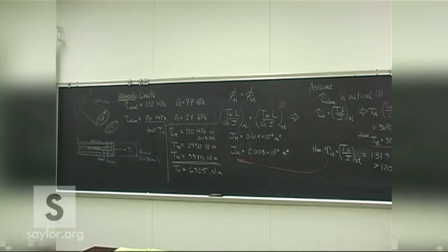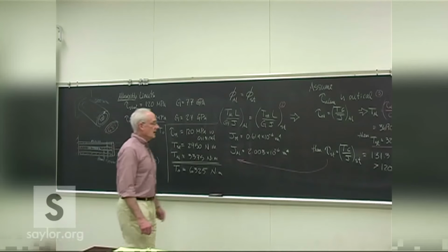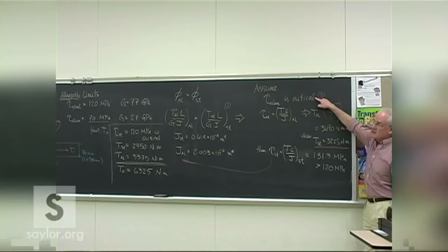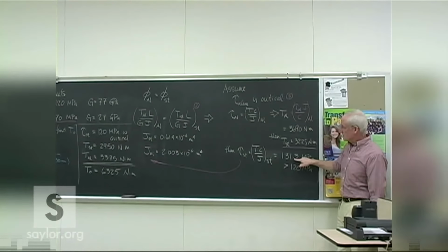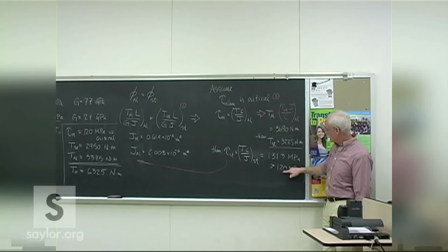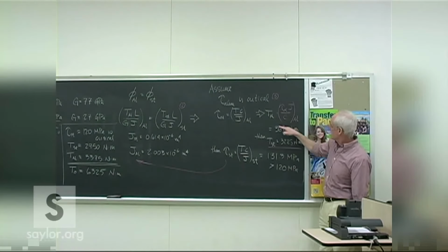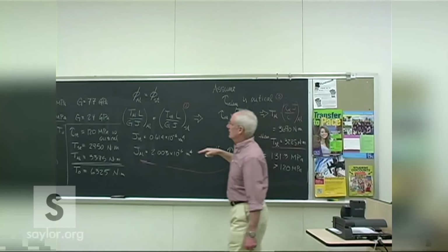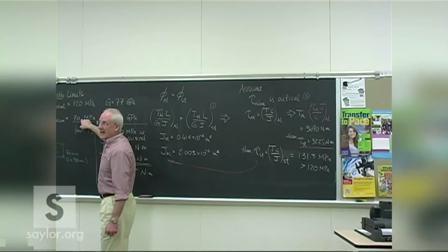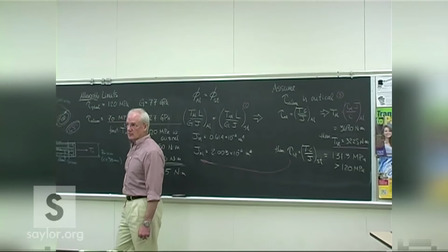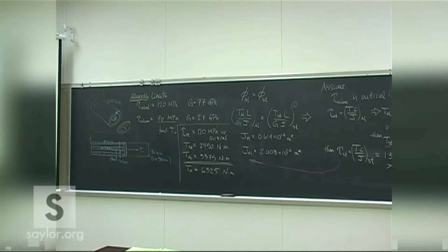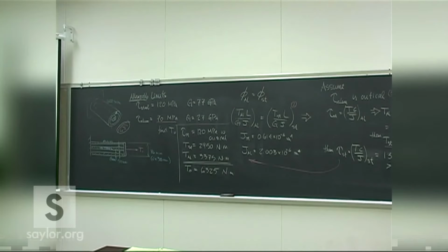Do we have to check that at the end like we did with the aluminum? No, because we know it's not. Being at the aluminum limit pushed us over the steel limit. So we dropped down on the steel, which is automatically going to take all the loads off to a lower level anyway, which means we're automatically below the load on the aluminum anyway. So you don't need to check it. You might need to know it for some reason, but you don't need to check it.